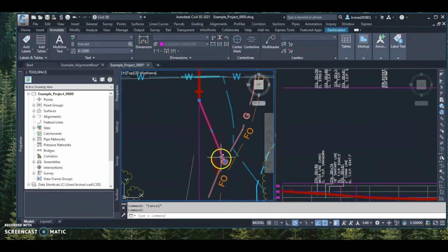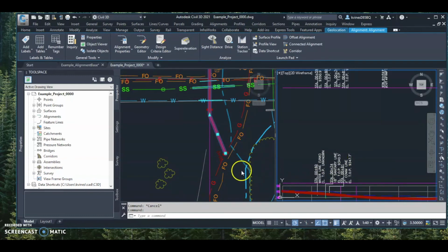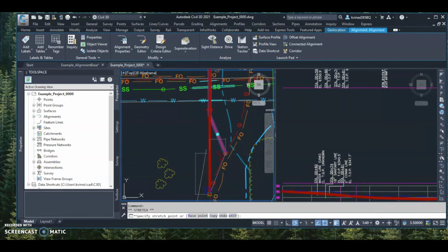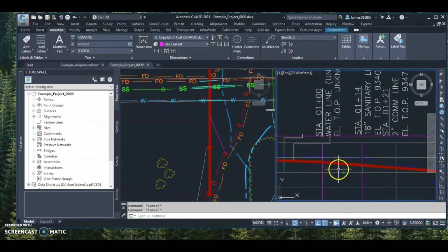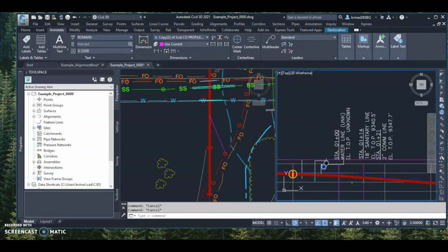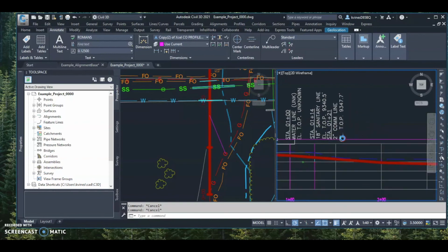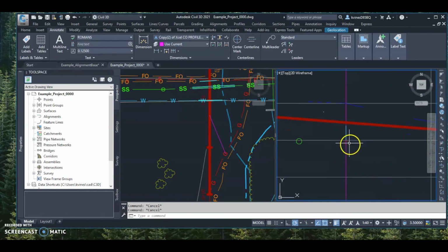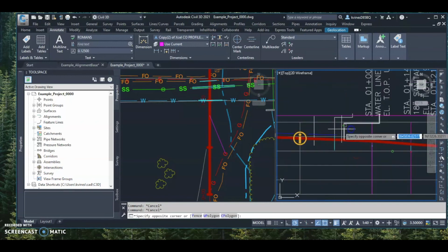And I will kind of demonstrate that now. So I'll take this alignment and keep an eye over here. If I take this alignment and I stretch it down here, you'll see that the pipe network components and all of the labels in the stationing and profile band did move. What did not move is this dummy gas line here, because it's not a smart feature.